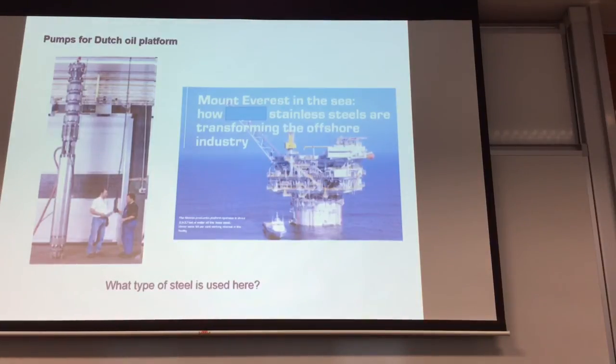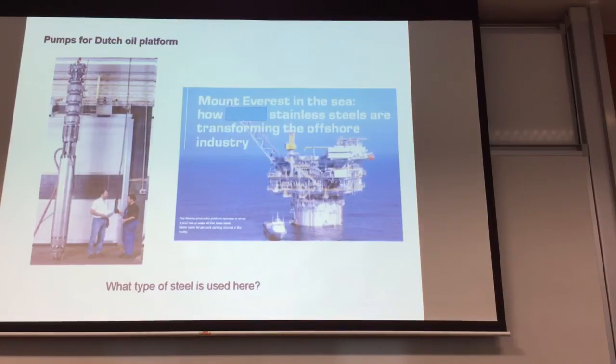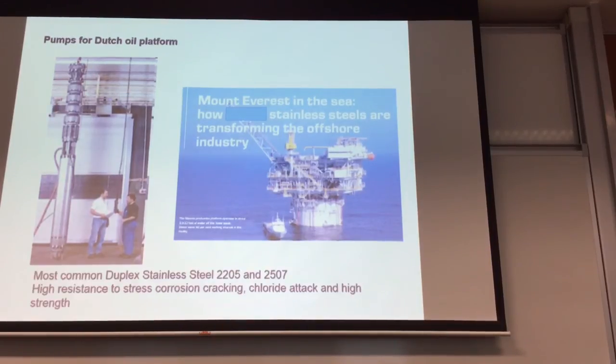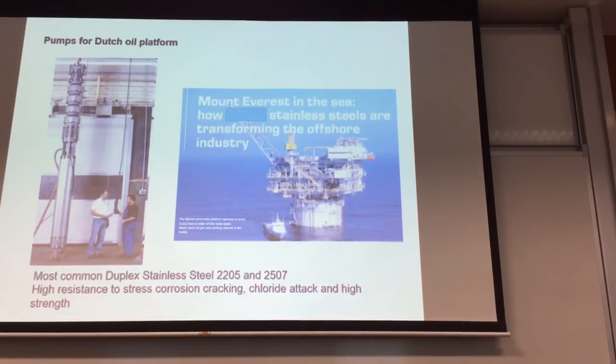Oil platform. Components in the oil platform. Use stainless steel. Talk about seawater. Most likely you'll be using a duplex. By the way, stress corrosion cracking is something that you find in stainless steel. That might be based on the problem of stress corrosion.